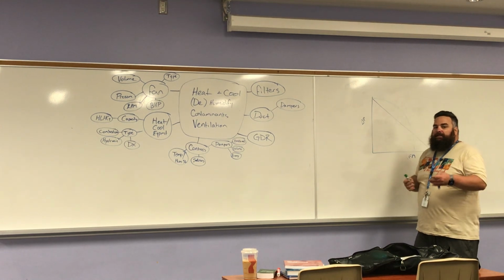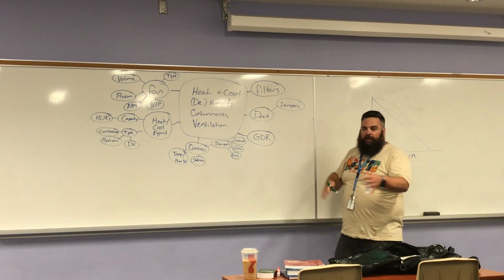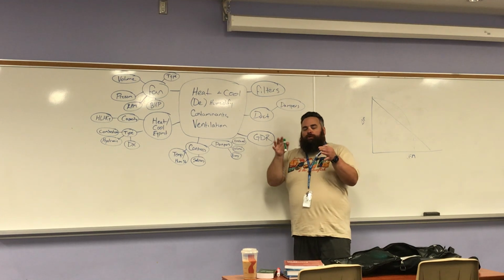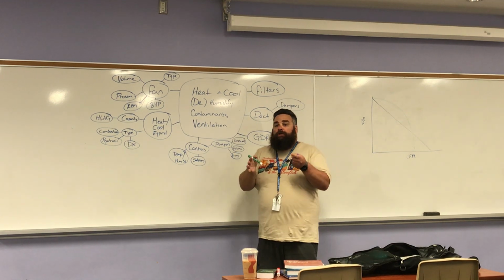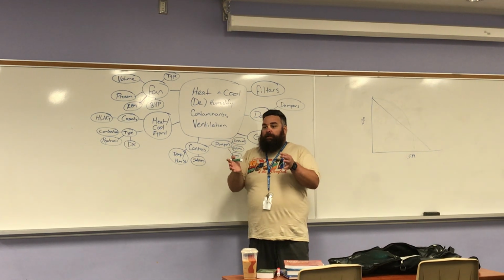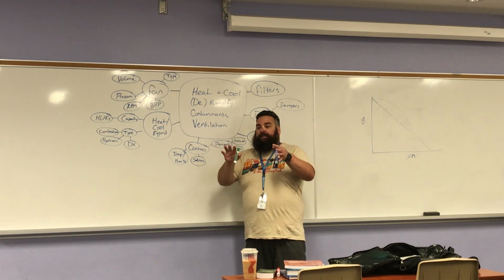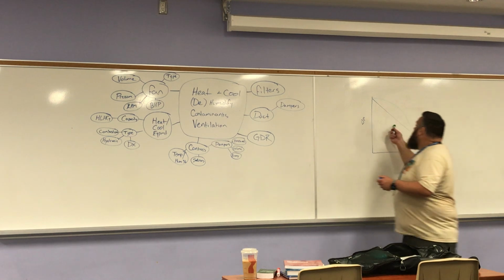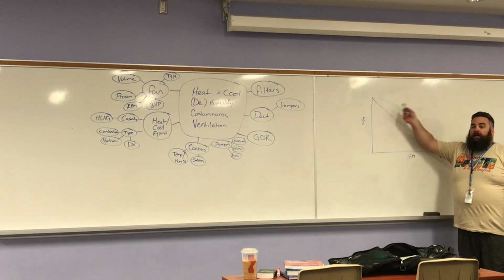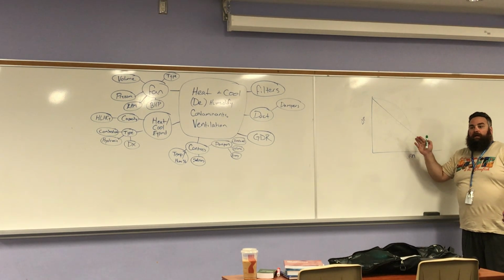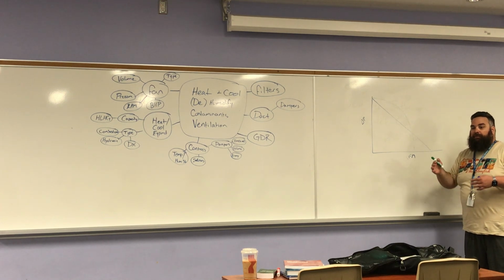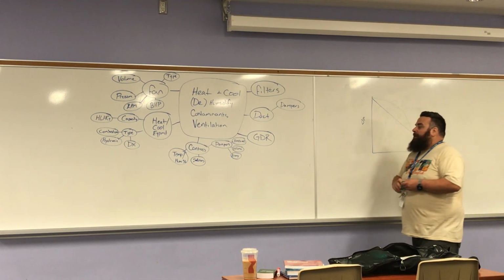And what that means is if you're trying to do a mixing situation like an economizer, you have to select your dampers so they have the same amount of authority, or a complementary authority, because you want those to work together. If one's linear and one's not, then that damper position is going to let a different amount of air through and they might not match.